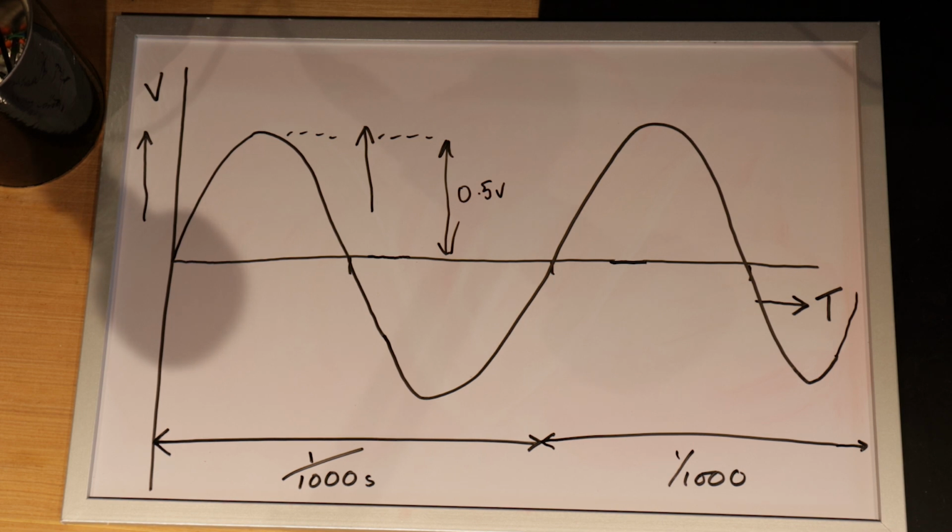The reason that we want to watch the signal as it goes through is because there may be faults within the amplifier. So for example, there's no sound coming out of the amplifier. You can inject a 1 kilohertz tone into the input. You can then, with the end of the oscilloscope probe, touch the pin of the preamp tube where it comes in and see that the signal is reaching the tube.